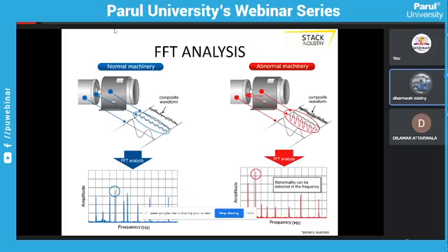If we connect a vibration meter to a motor, all vibration of the drum, shaft, back bearing, and front bearing will be coming on the body, so on the body we will measure the vibration. If there is any abnormality, then according to the FFT analysis or FFT graph, we will get a spike. That VRMS is calculated by a vibration meter, vibration analyzer or vibration sensor and the data is given to the PLC or analyzer that there is some problem. So all the analyzers or vibration inspecting devices work mostly in industry on FFT analysis only.